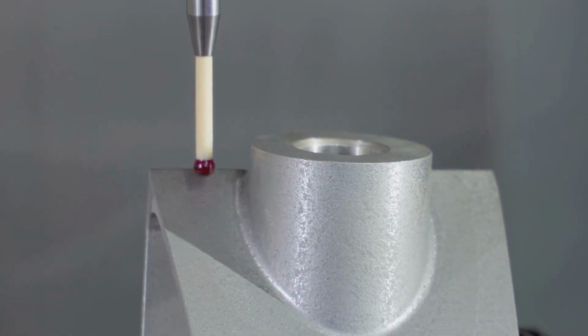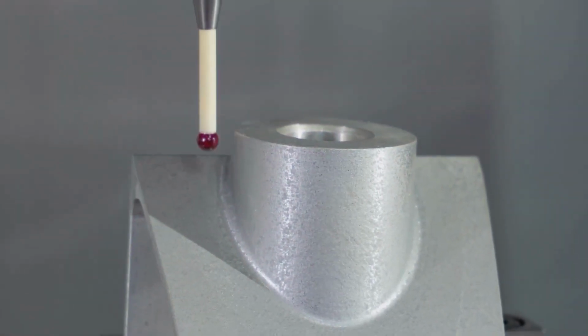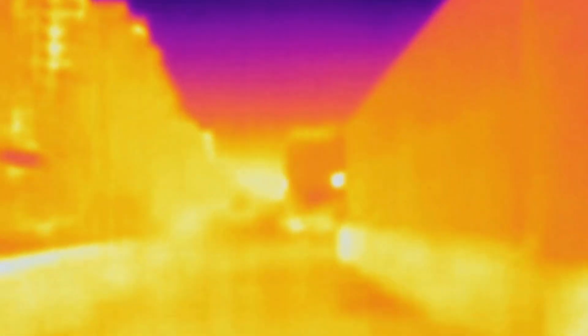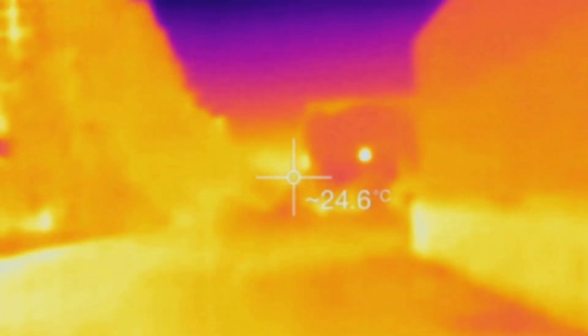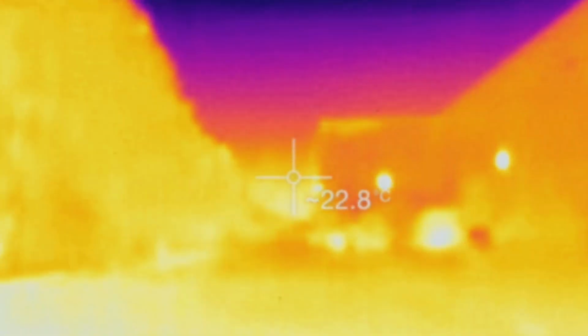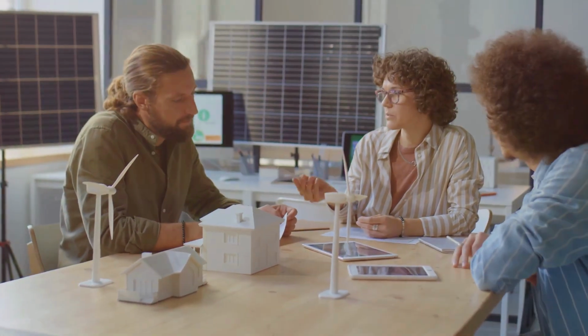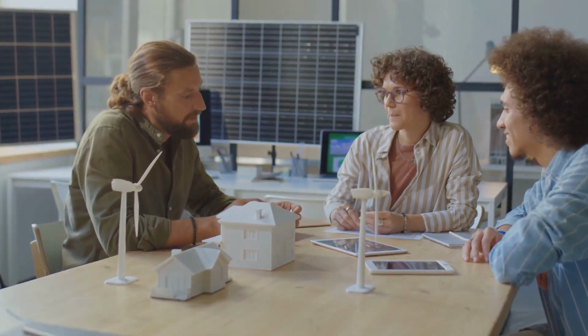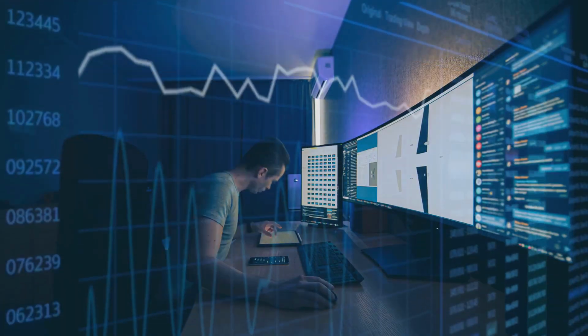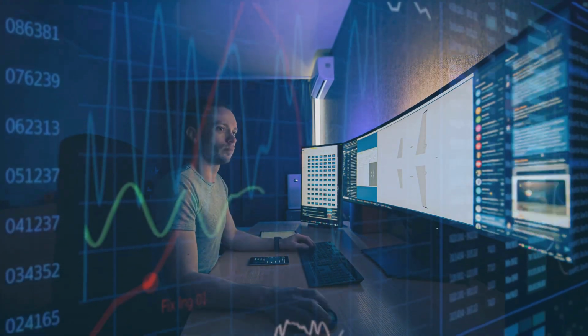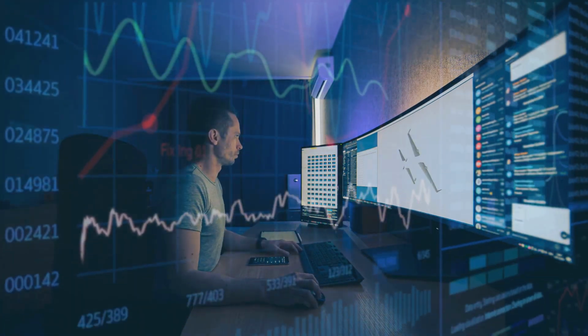Optical thickness is a key factor in this decision-making process. For optically thin media, where radiation travels relatively freely, the S2S model might suffice. As the medium becomes optically thicker, models like DO, DTRM or P1 become more suitable. For extremely thick media, the Rosseland model offers a computationally efficient approach.